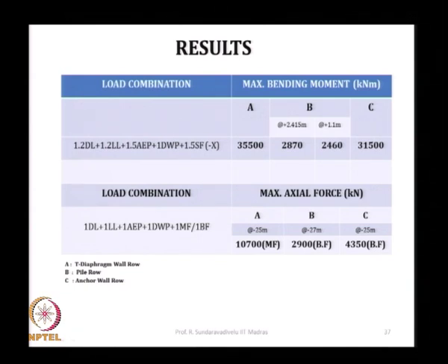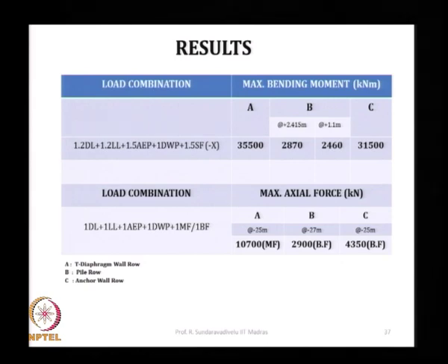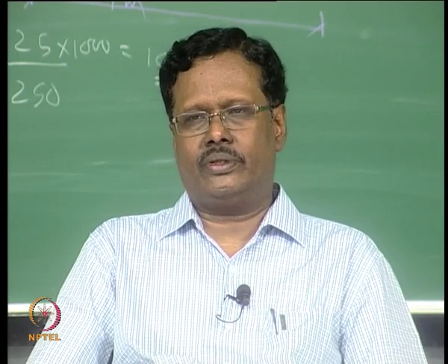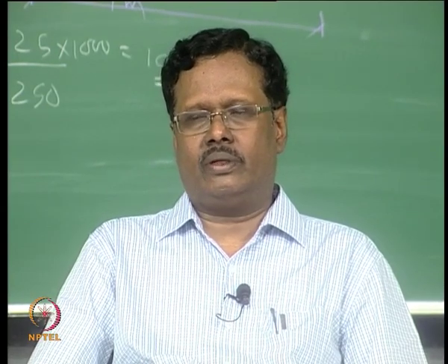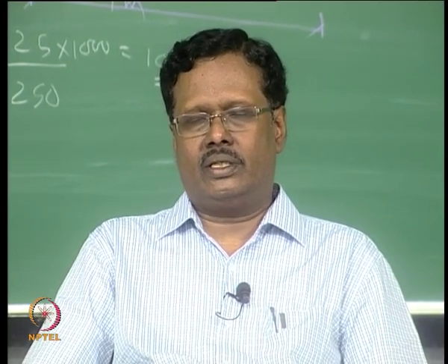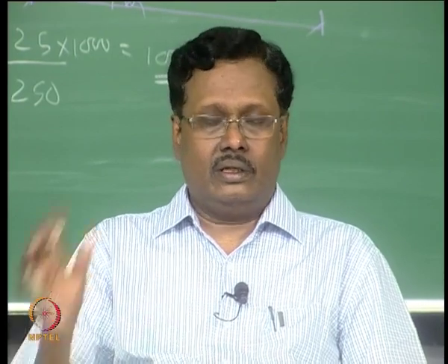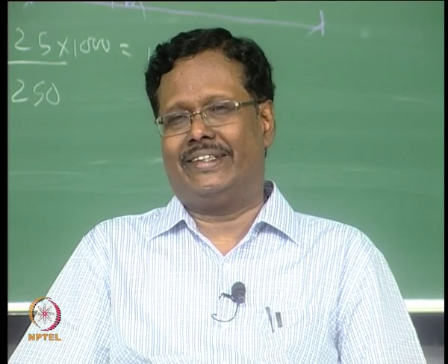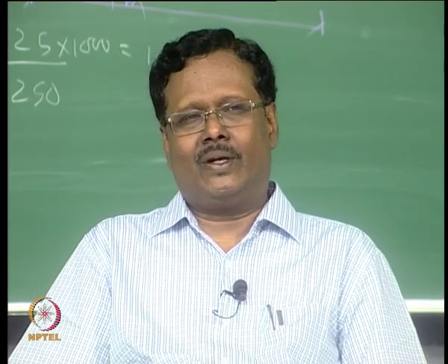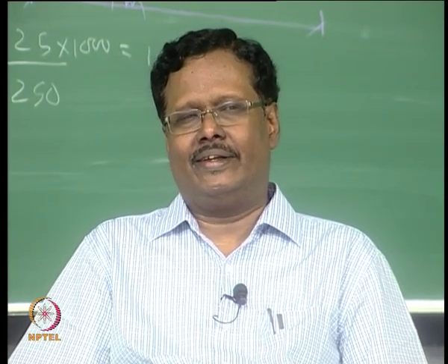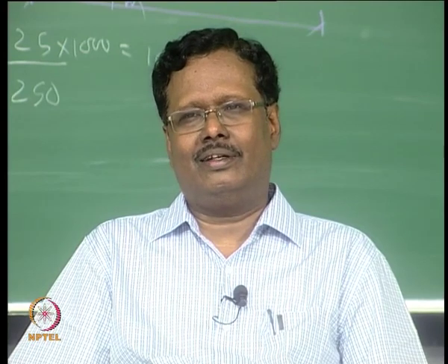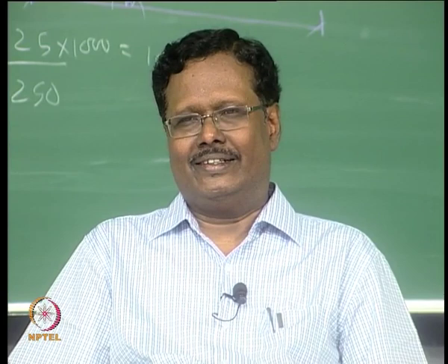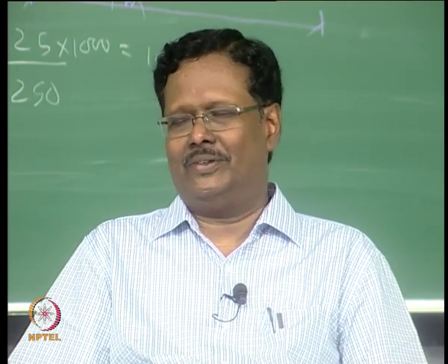Any doubt in this? You have different forces acting: dead load, live load, berthing force, mooring force, seismic force, active earth pressure, differential water pressure, and you have to consider different load combinations. How many combinations will we analyze, do you think? Guess a number.